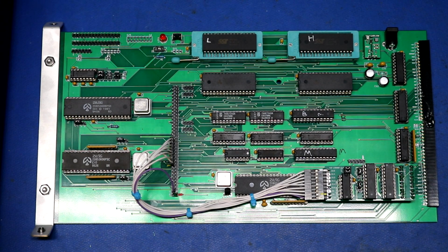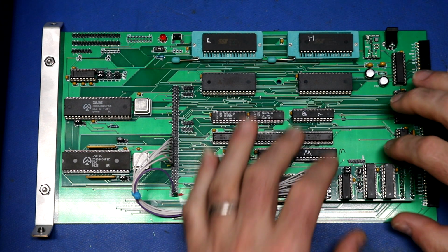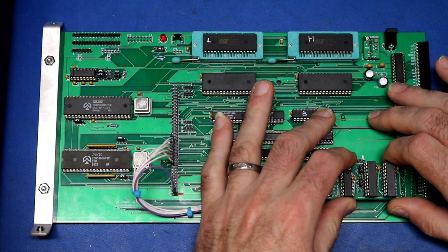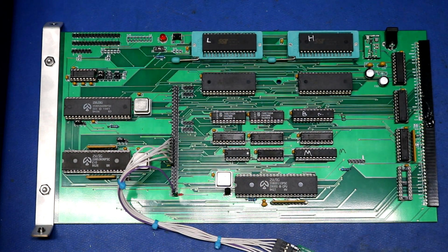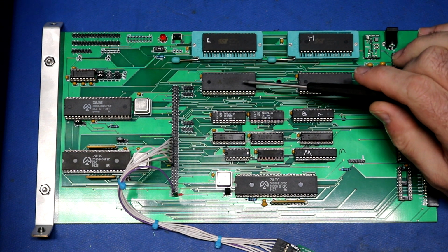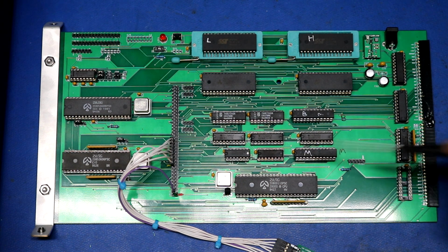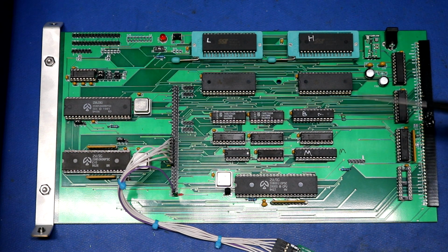Okay, here is the completed Z8000 CPU board. Here, let me pull this little piece loose so that we can see. Down here is the Zilog Z8000 CPU. Up here we have a couple of RAM chips giving us our 1 megabyte of RAM. We have some flash memory chips giving us our 1 megabyte of ROM. We've got the bus and memory programmable logic devices. We've got various transceivers over here that hook up to the H8 bus.